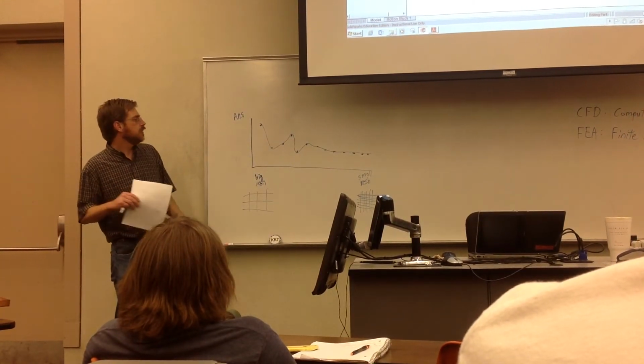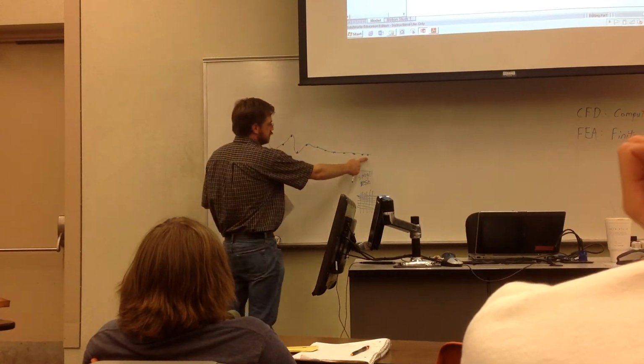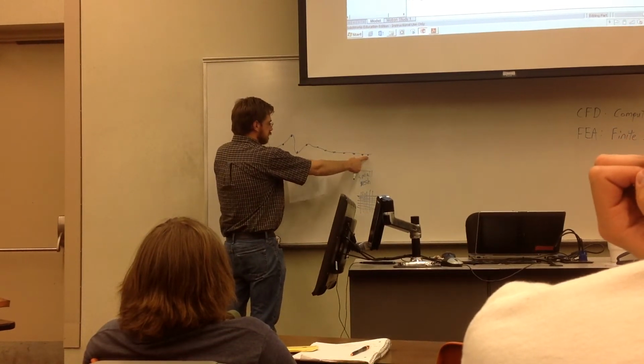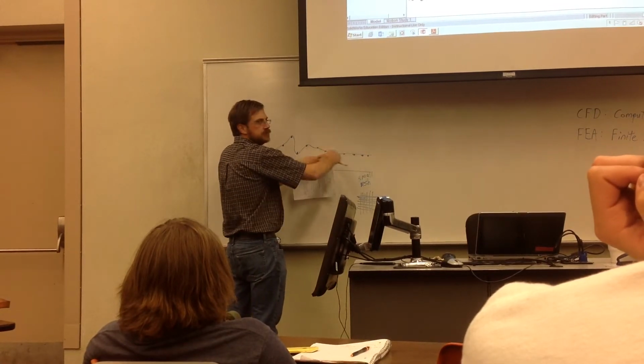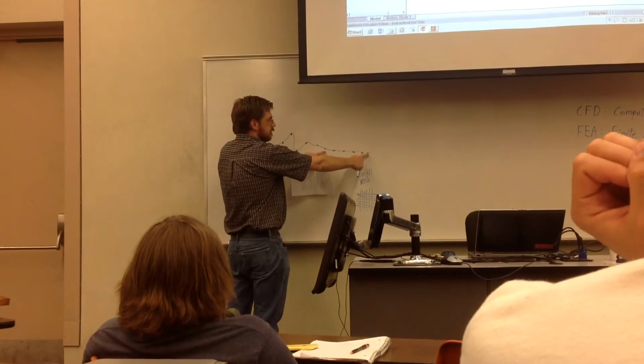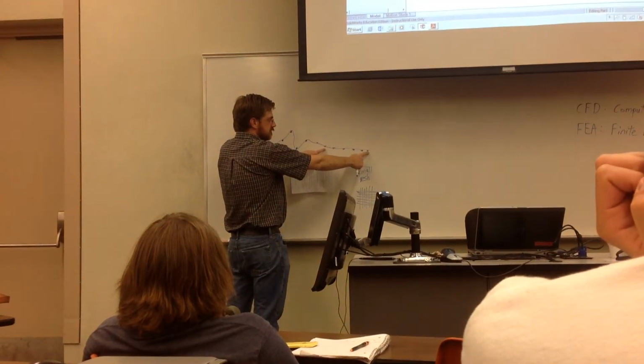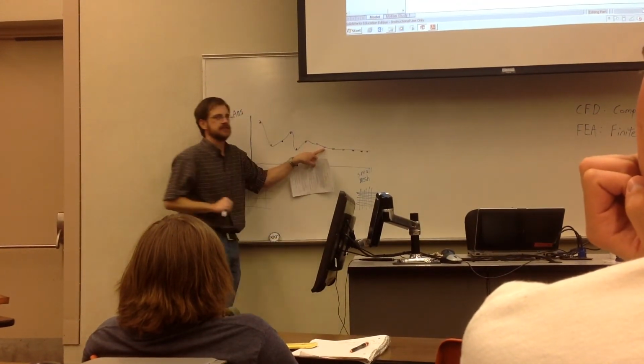Okay. Well, now let me ask, picking the smallest mesh, if we go with this one and compare it to this one, there's not a whole lot of numerical difference, right? But this one could take 100 times longer than this one to get an answer.